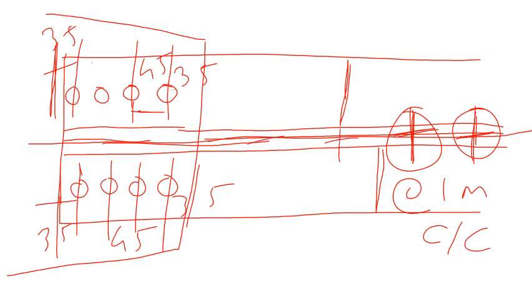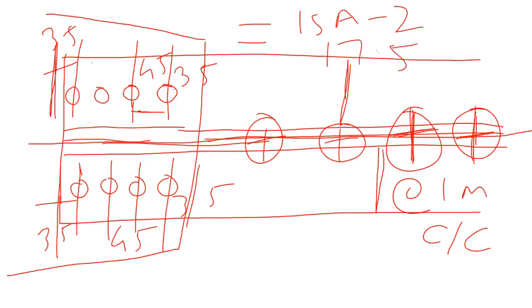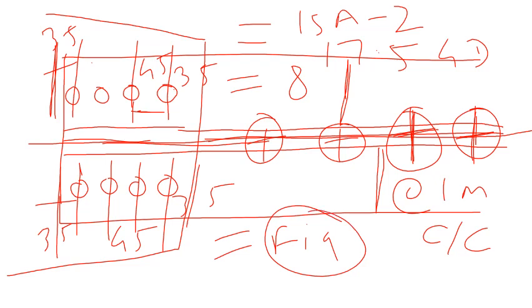So maybe we have this kind of tacking rivets. The distance between their centers should be 1 meter, and they will keep these ISA together. Now we have the size of the ISA, Indian 2 number, that is 50 into 80, 6 mm thickness. Then we have the diameter of the rivets, 17.5, that is the gross diameter. Then we have the number of rivets, that is 8, and then we have this figure that shows how to connect it to the gusset plate. So I believe we have everything and we are good with this problem. Thank you.